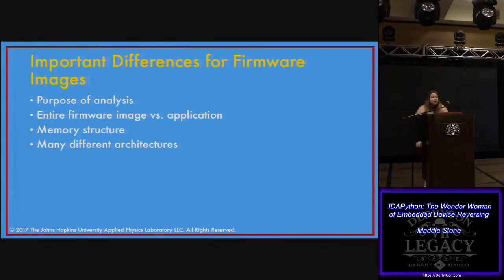All of this is where we want to focus instead of getting bogged down in some of the other support code. The other thing is that when you have an application you generally have a PE file or an ELF file that gives you a lot of information. Not the case when you're looking at embedded. You've probably just pulled or extracted the firmware and it's a binary blob. So how are you going to figure out what's your code, what's data, where does RAM live? How do all these pieces interact? And that's your job to do. Nothing's there to tell you what that looks like. So we need some scripts to help us say, cool, let's define all of this as code, let's define all of this as data, things like that.